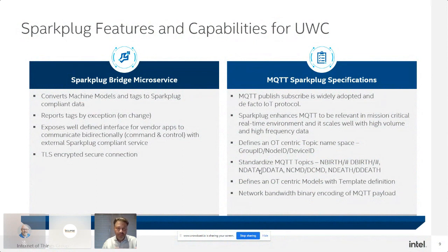There's a simple model for the life cycle of communications that is generally different from what you have for a Sparkplug or an OPC UA specification for an edge to control room or edge to cloud type of implementation. So there is a need for a bridge. We do not have the Sparkplug specification running natively inside the device. But in the bridge, we handle the major pieces of the contract that you need for the Sparkplug specification: birth, death, data, commands, etc.